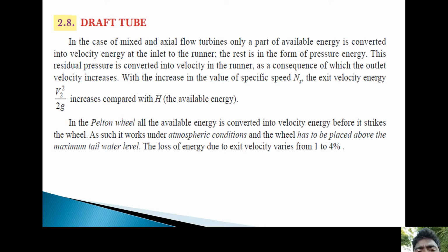The rest is in the form of pressure energy. This pressure is converted into velocity in the runner, as a consequence of which the outlet velocity increases.